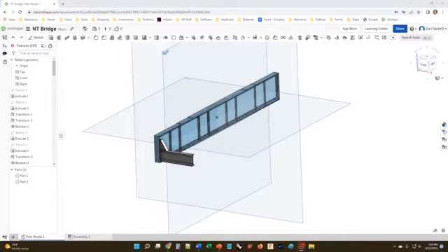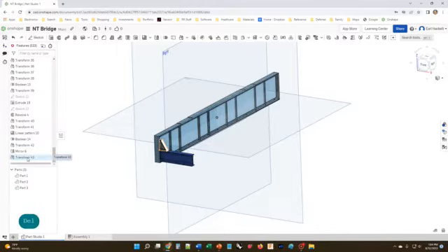It was pretty obvious while doing this drawing on the show that I messed up. I used the cross-sectional dimensions for the stringer rather than the floor beam. Mistakes are unavoidable. Even if you don't make a mistake, you often want to change the design. In both cases, when working in a history-based system like Onshape, you back up through the history until you reach a point where you can move forward again with the changes.